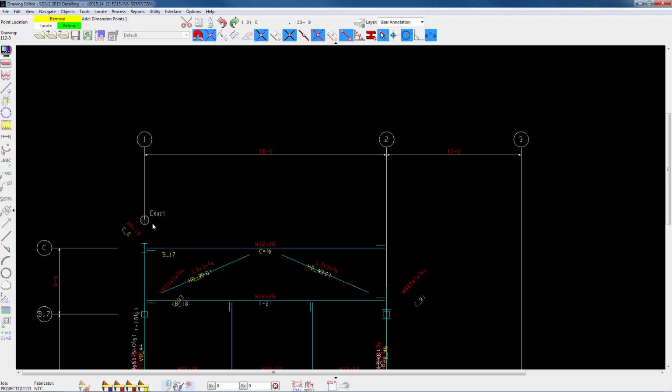So in this case here, if we pick that point and then using your location icons up here, if you leave it on auto, it'll find the work point of that brace coming in here. And then over here, right click for return and then type a dimension horizontal. If I pick a free point there, adds on that dimension.